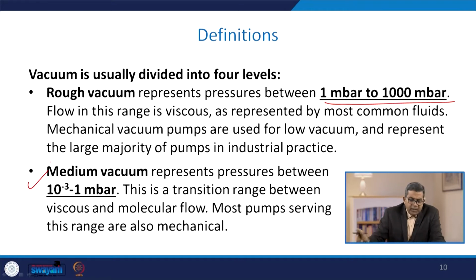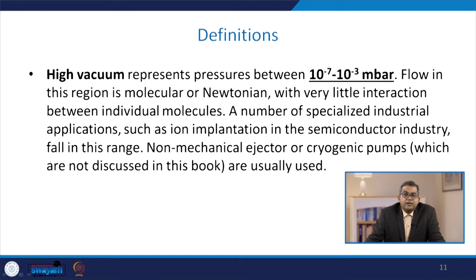Next is the medium vacuum. This represents pressures between 10 to the power minus 3 and 1 millibar. This is a transition range between viscous and molecular flow. Most pumps serving this range are also mechanical.